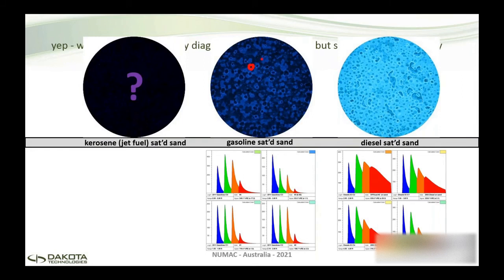Now, coarse grained materials are going to have these large voids where this NAPL can squish right up to the sapphire window. This is taken up against a sapphire window. Clays and silts have such tiny, tiny particles that they kind of hog up the window, and they don't allow any of these big, beautiful globules to press themselves up against the window, and the penetration depth is therefore very limited down into that NAPL in each pore space. Okay.